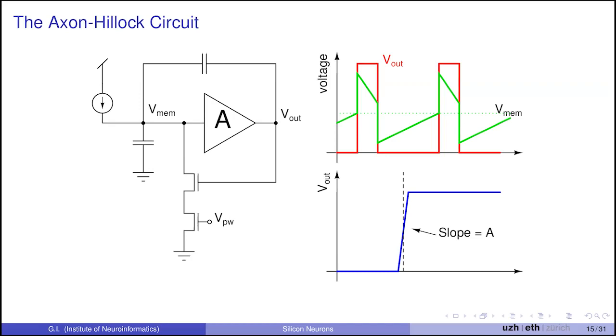There are different techniques for avoiding device mismatch. Typically, we try to make analog transistors large, and that helps in reducing device mismatch. Increasing the area, the W and the L of the transistor, decreases the effect of device mismatch. But also having dummy copies or multiple copies of the same instance is another trick to reduce mismatch. And so one can combine the two techniques.